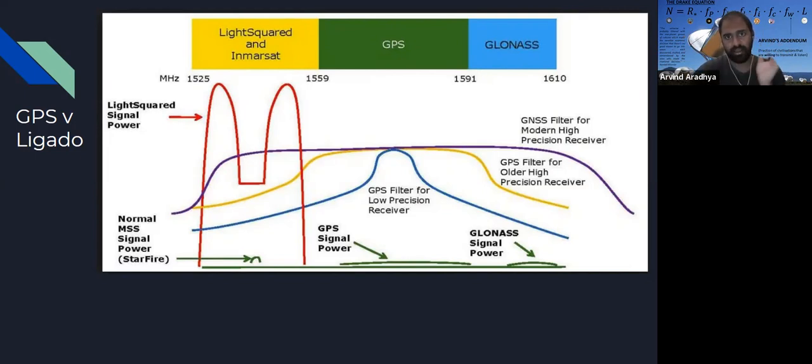So, if you had an active transmitter, let's say I'm authorized to transmit at 100 megahertz, and I do all my due diligence and build a system that transmits at 100 megahertz. Despite all my efforts, because of this nonlinear modulation, there will be certain harmonics, called harmonics because they occur in multiples of the frequency we're transmitting.